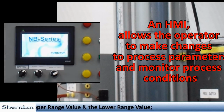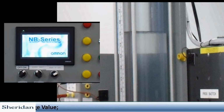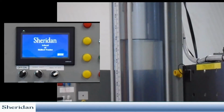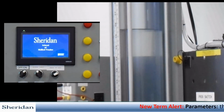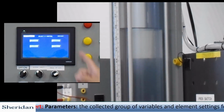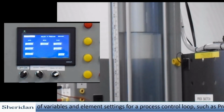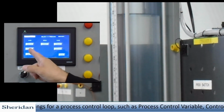In the last lab, we calibrated our transmitter so that we had a lower range value of 2 inches and an upper range value of 20 inches. Without touching the knobs, we rewired it to be controlled by our HMI and our PLC. So the first step you're going to do is turn the system on. You're going to hit continue and you're given 4 menu choices. So we want level. We've already done the point level lab, so that won't be necessary, but we do want to do the continuous lab.